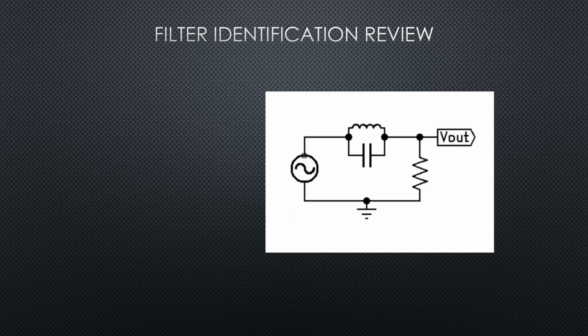Okay, here is a very similar circuit, but now the reactive components are in parallel. So let's draw our curve. At low frequencies, the inductor is going to act like a short. We're going to have a maximum current situation if the inductor is acting like a short, and we'll have all the voltage at the resistor, at the output.